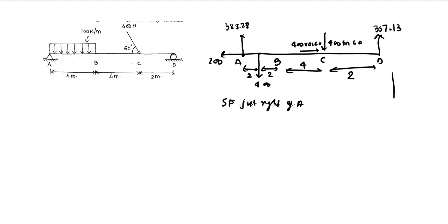Firstly, let us get clear with the sign convention. We have shear forces. Let's say you are considering forces on the left of the cross section. Then upward forces on the left of the cross section should be positive, and downward forces should be negative. If you are considering forces on the right side, then upward forces should be negative and downward forces should be positive. Just reverse the left side one.